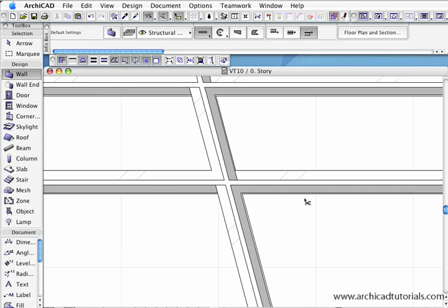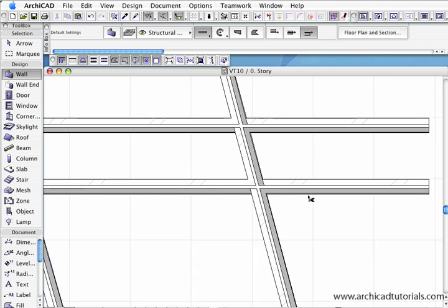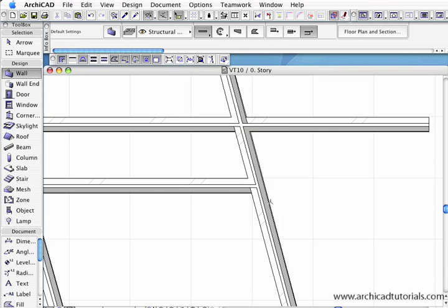Now if I hold the Control key down, as it rolls over either edge of the wall, it becomes a black scissor icon, which means it can actually trim the wall. But you don't use the scissor part or the mouth part of the scissors to cut the wall, because they're not really scissors. So as the pointy end, or where the arrow part of the icon passes over the wall, if I click, then it will trim back the closest intersecting line or wall or object to where I just clicked to trim.